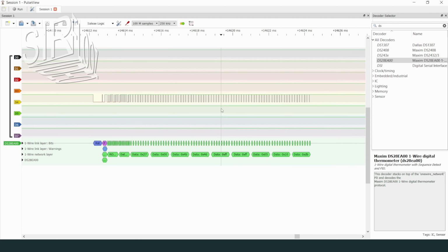In the other data packet, the sensor sends the temperature as 2's complement with sign. This data packet contains the temperature plus 19 degrees Celsius.